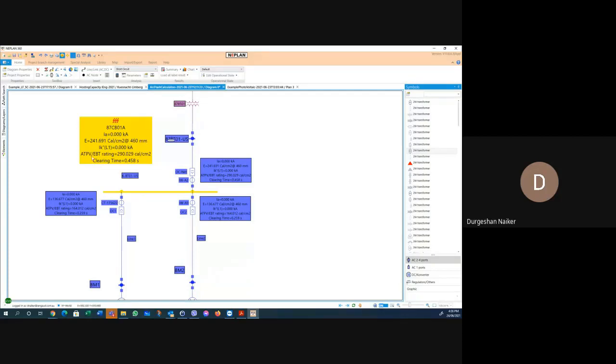The ATPV and EBT, I think ATPV stands for arc thermal performance value, and EBT is energy break open threshold. These are the ratings people look for when designing the uniforms. What should they be wearing? It also gives us the energy level at 460 mm away from this bus bar.